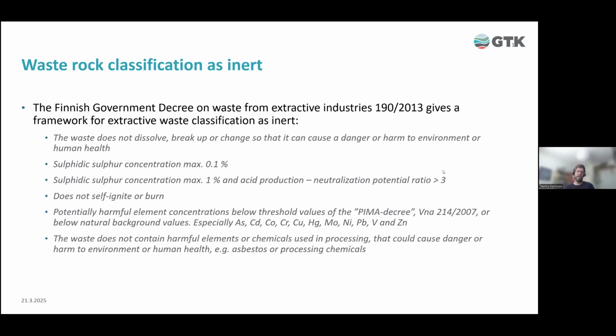The Finnish government decree on waste from extractive industry gives a framework for extractive waste classification as inert. Basically, the decree says that the waste shouldn't dissolve or break up or change so that it can cause danger or harm to environment or human health. Sulfidic sulfur concentration should be maximum 0.1%, or 1% if the acid production neutralization potential ratio is higher than 3.